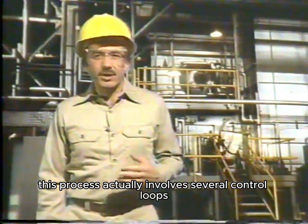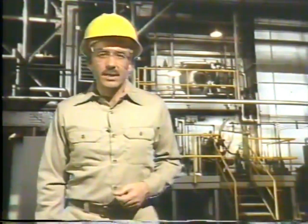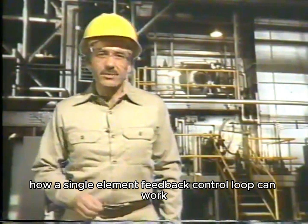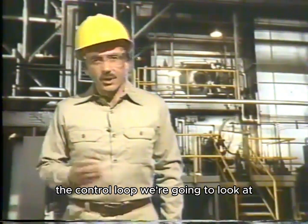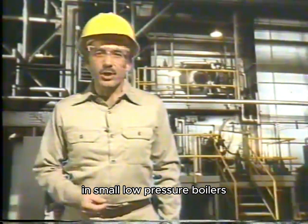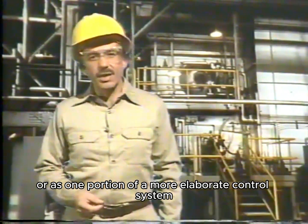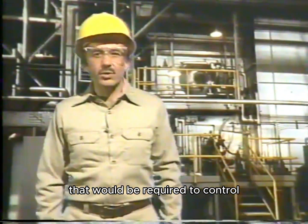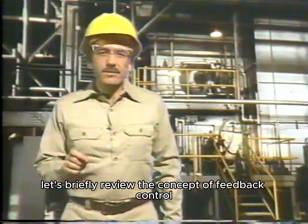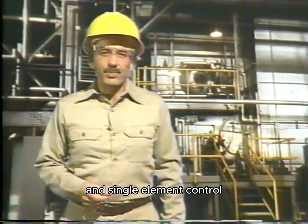Now, this process actually involves several control loops working together to control air, fuel, and water. For our purposes, we're going to look at just one part of this system to see how a single element feedback control loop can work. The control loop we're going to look at can be used to control drum level in small, low-pressure boilers having relatively stable flow characteristics, or as one portion of a more elaborate control system that would be required to control drum level in a large boiler. But before we do that, let's briefly review the concepts of feedback control and single element control.